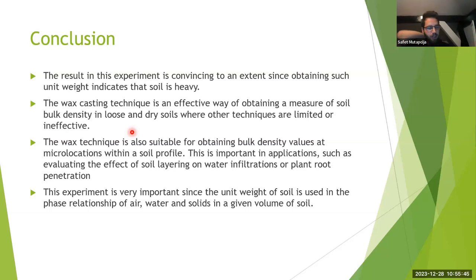You dig your trench for the pipeline to some depth, for example 1 meter, and you're going to put your pipes at like 0.8 meter. On those 20 centimeters of soil, you're going to do aggregate, like really fine soils and aggregate compaction.